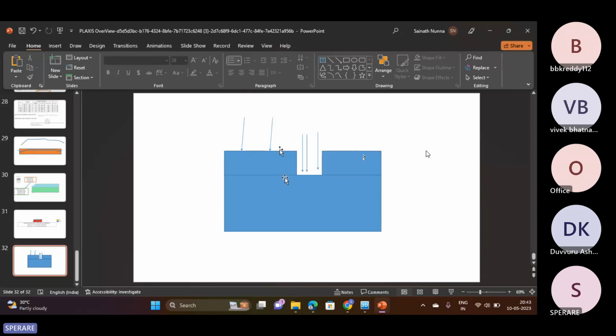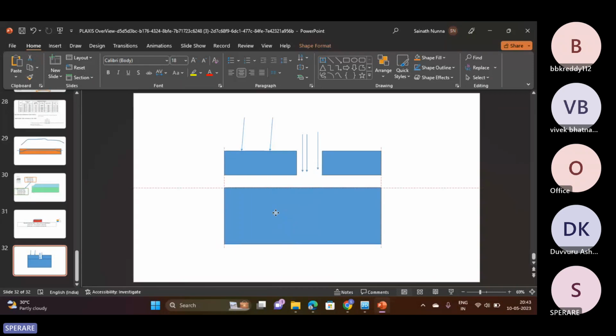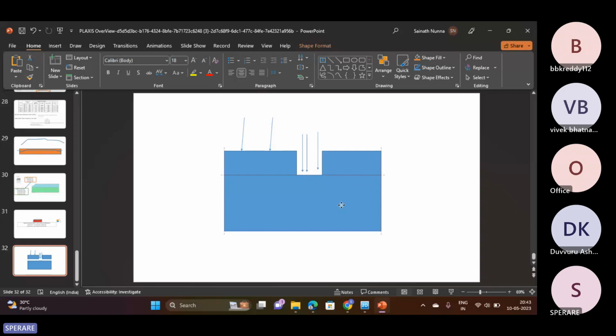So now, simply to implement this kind of scenario, what I can do is go for the initial material properties itself with small changes. If by chance you have the material properties, I can consider these changes. But if you have only the initial material properties, first do only this one, go with the KO procedure, and then attach this and simulate what happened on the site for these many days.